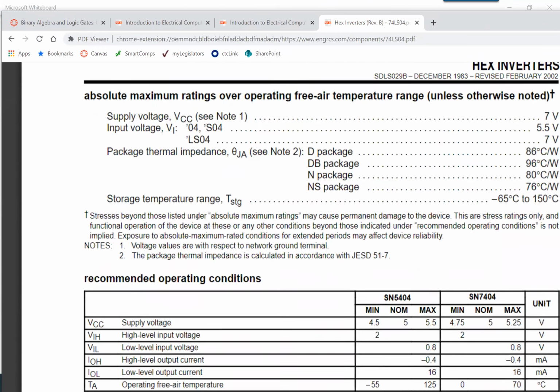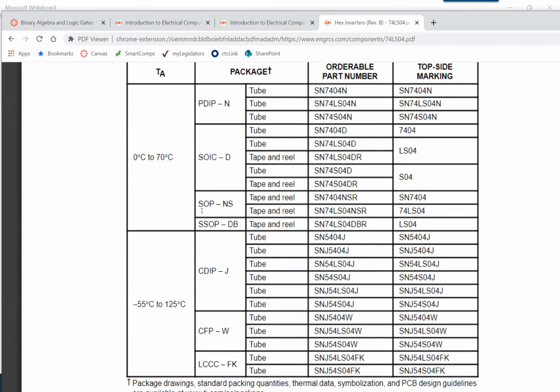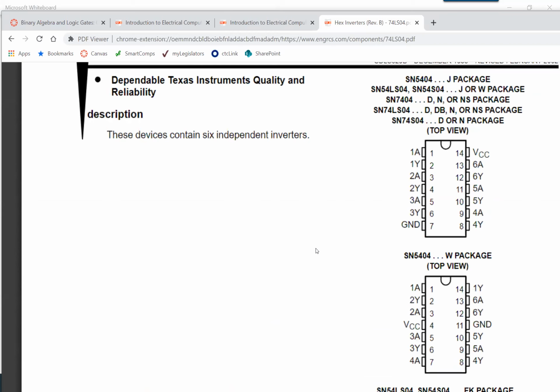One thing I forgot to mention, and I'll go back up here to mention it, is that when you are using these chips, almost all of them will require you to connect the ground and VCC. VCC is 5 volts for the parts we're using here. So that's important: before this part does anything, you have to connect that to 5 volts and you have to connect that to a ground before it starts working, okay? I think that's about all we have for this.